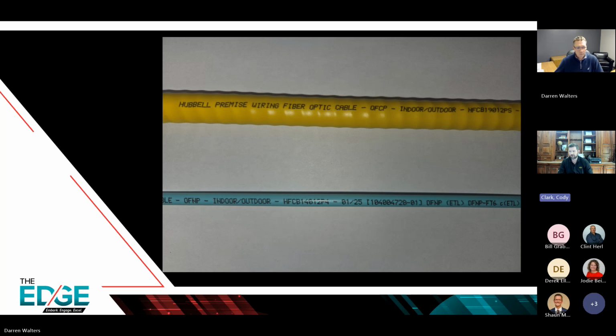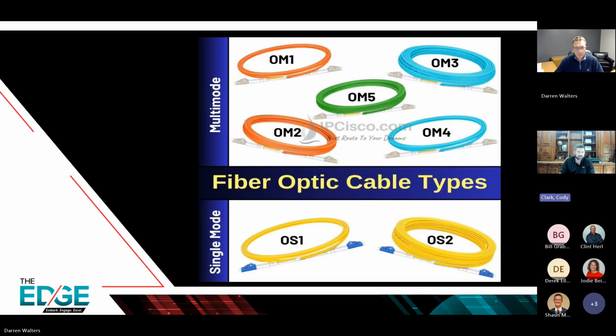This one has an indoor-outdoor rating, so it's a little different than what was shown in the slides, but it's suited for UV and wet environments, and also plenum-rated airspaces. So there are combined cable types. With fiber, you can usually identify the series of fiber based on the color coding. Outdoor cables are often black. The indoor-outdoor ones that we just showed you are color coded. When they're black, you're going to have to refer to the jacket. But if they're color coded, you should be able to easily identify: are they an OM3, OM4 laser optimized? Are they single mode, if they're yellow?